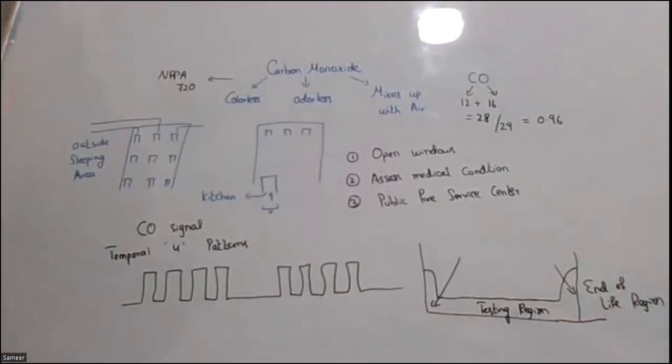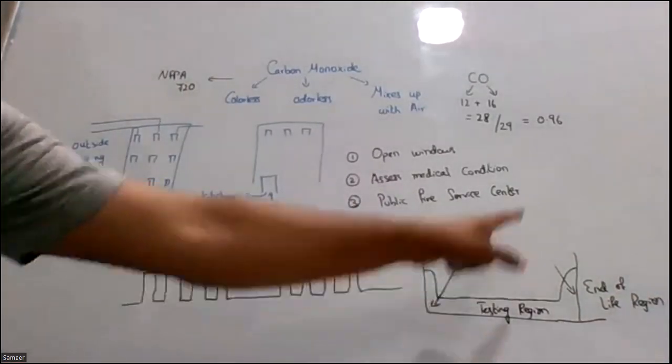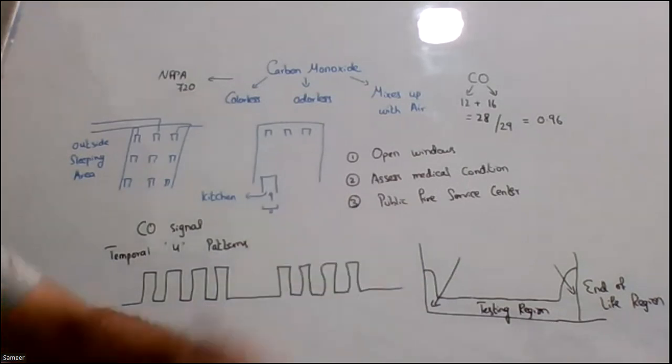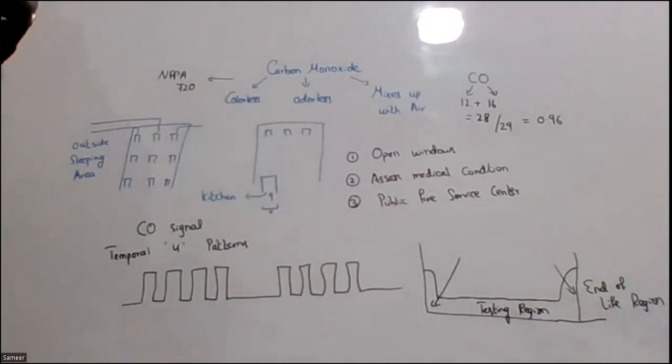Okay, so this is a type of path. That is the bathtub curve. To identify the lifetime curves, as I said, we usually calculate 3% per year. At the end of 4 years, 12% of faults are going to be there. Based on that, we need to see how many hardware units are being repaired, and how many are required for each fault: a single hardware, or for each fault 2 or 3 hardwares. So based on that, we make this curve.